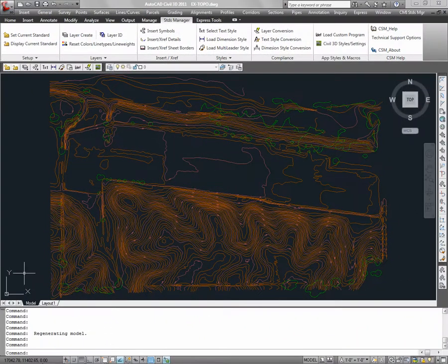One of the easiest ways to create consistency in your drawings using CAD Standards Manager is with layers. CAD Standards Manager can be used to create new, consistent layers or to update existing drawings so that their layers become standard. In this demonstration, I'll show you some of the layer functionality included within Standards Manager. First, I'll show you Layer ID.